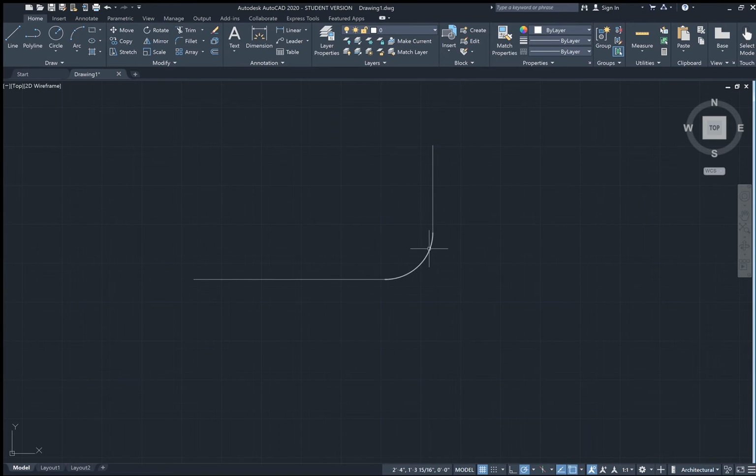And so that's the fillet command. The last one I want to go over, actually, there's 2 more. This is the offset command, very, very useful. Now it says specify the offset distance, and what this means is basically if you select a line, it'll offset and create another line that is a given distance away.